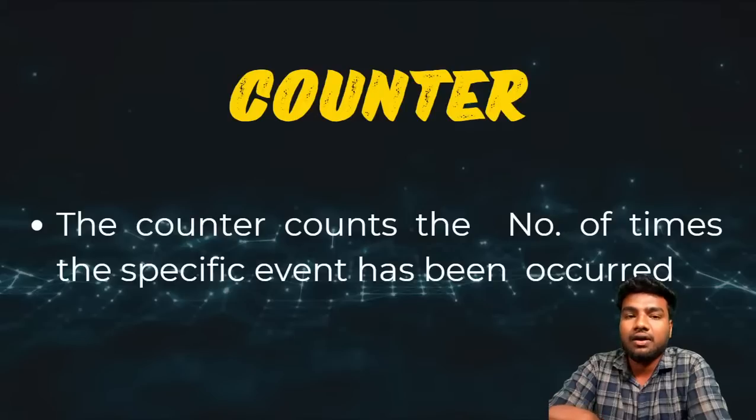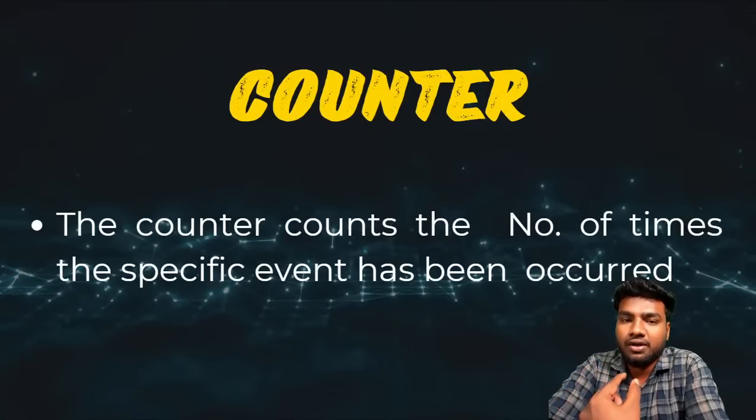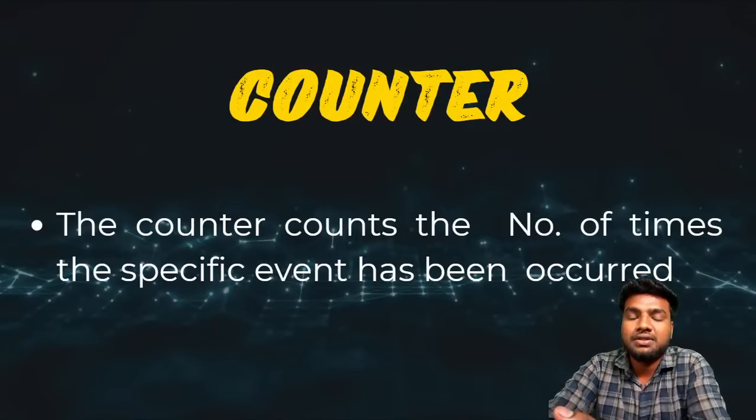For counting purposes we must use sequential logic like flip-flops. Flip-flops are fully based on the clock. They receive and store data, and give output based on the clock pulses. It may be a negative edge or a positive edge. Based on the clock pulses only, it will operate like a sequential circuit.